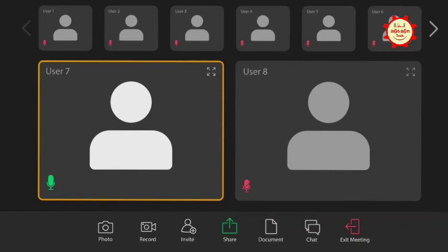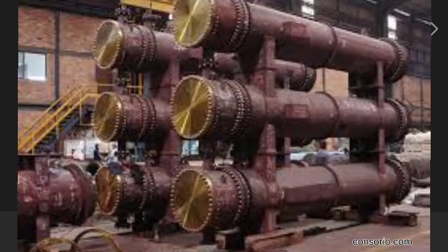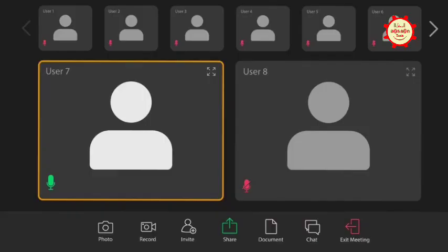In a stack, normally one exchanger is mounted on the other. So whatever loads there are, you transfer them to the bottom saddle. I have calculated the top exchanger load for each saddle for operating condition, empty condition, and hydro test condition. Similarly for wind loads, you have to consider the total height of the equipment, meaning the height of both exchangers, which is helpful for moment and wind, because the total height is used in the wind factor. How to calculate wind?